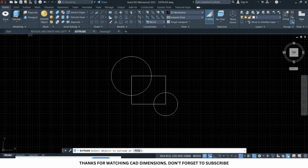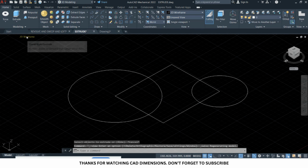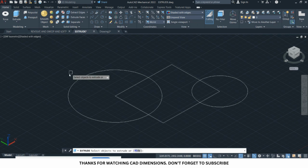Okay, so if I select extrude now, for the purpose of getting a proper understanding, let me change it to southwest isometric and also change the 2D wireframe to shaded with edges. All right, so come back to extrude again. The extrude helps you to extrude with respect to the shape. Now there is a difference between the press pull and the extrude. The press pull actually extrudes with respect to regions. Now if you come to the extrude, you have a mode here.